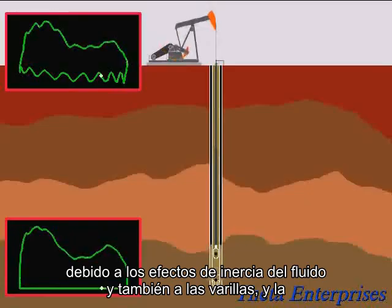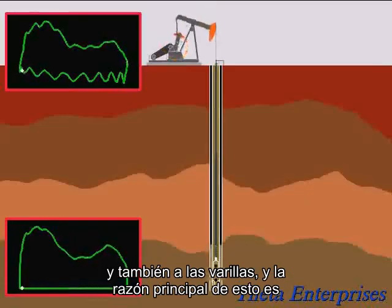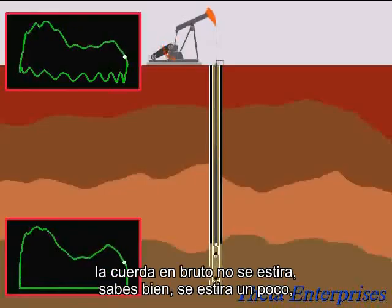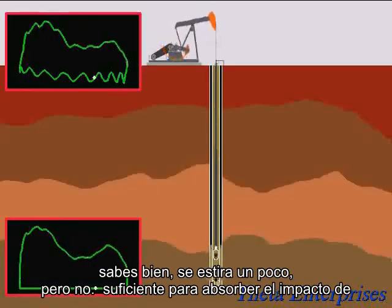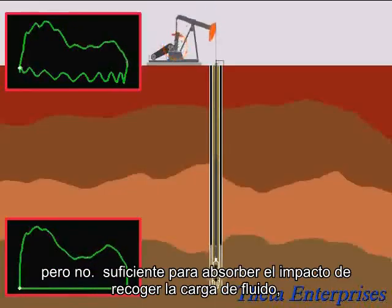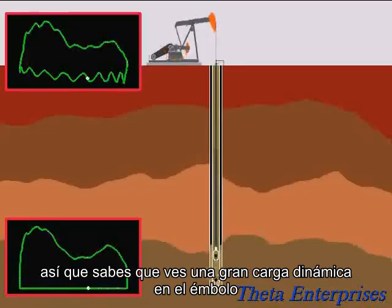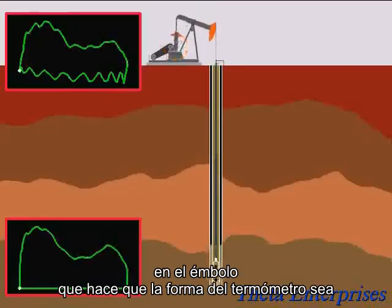One of the primary reasons for that is because the rod string doesn't stretch. Well, it stretches a little bit, but not enough to absorb the shock of picking up the fluid load. So you see a large dynamic load on the plunger.